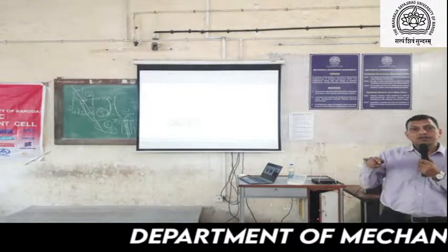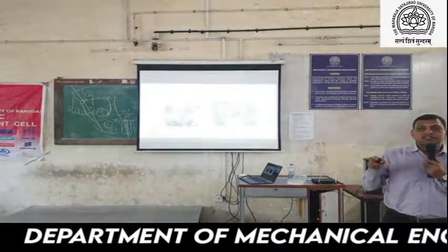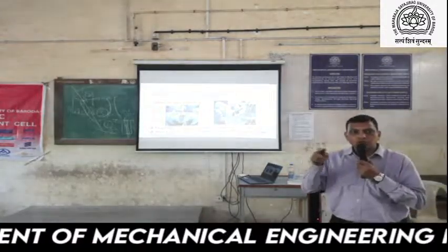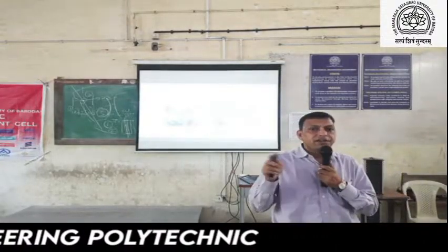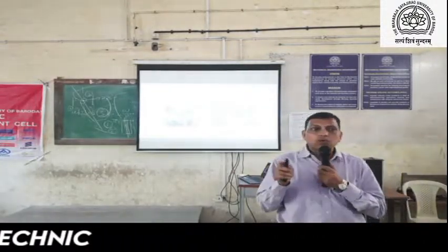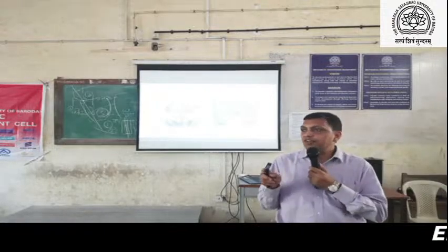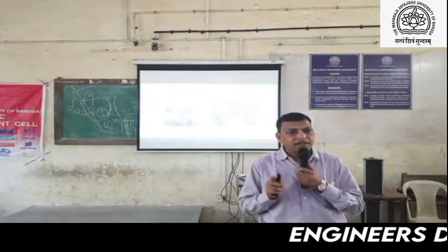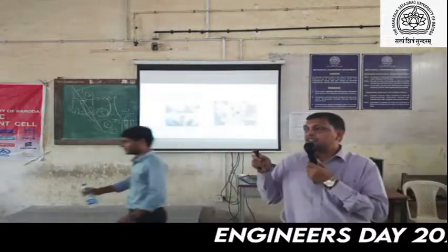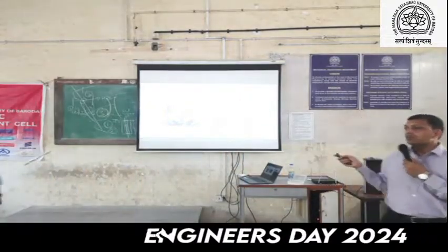During heat treatment, we have already considered some allowances. If the final tooth thickness is 8 mm, then during machining we have to consider a tooth thickness of 8.6 or 8.8 mm. That can be finalized at the time of the grinding operation.